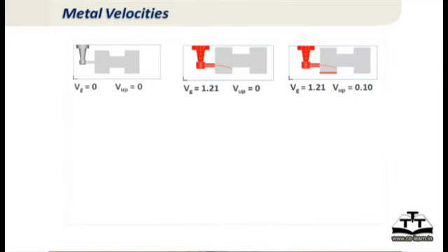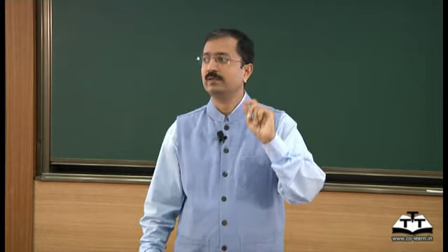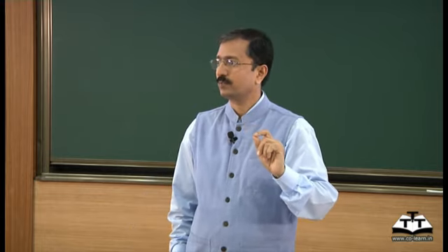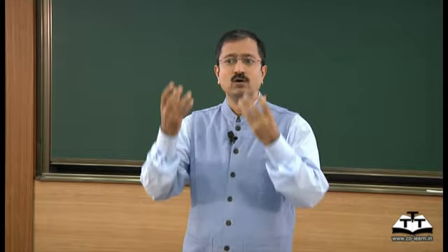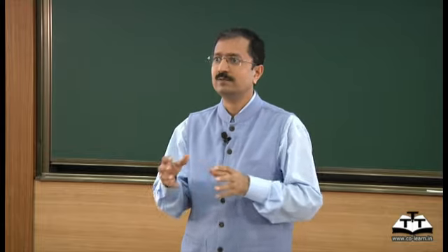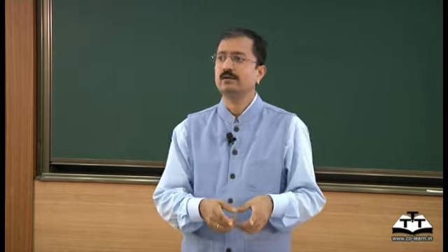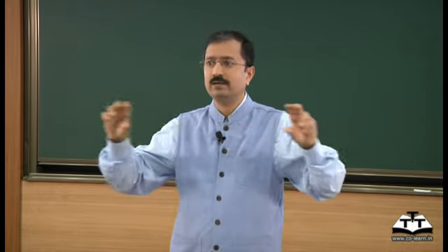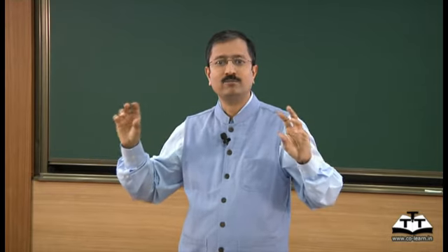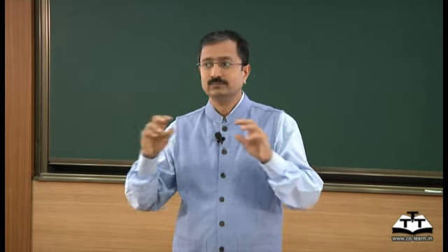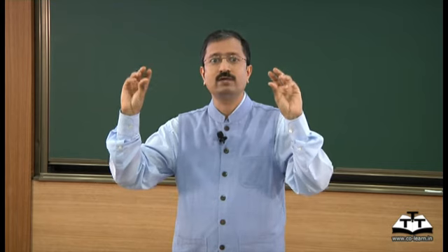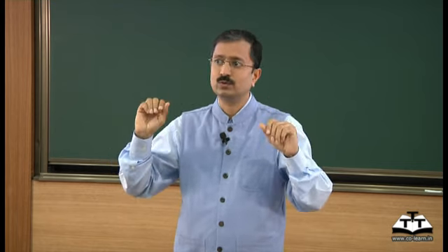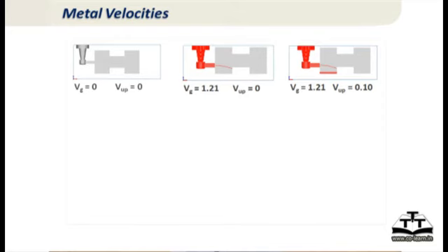We can also track the vertical velocity of metal rise in the mold, because we talked about lap formation and a few other problems. Even blowholes depend on how fast the metal is rising in the mold. So some problems can be caught if we track the vertical rise of metal in the mold. Wherever you have a sudden big horizontal area, you can have a problem of metal slowing down vertical velocity. If it slows down, venting is good, but then lap formation and blowholes can form.